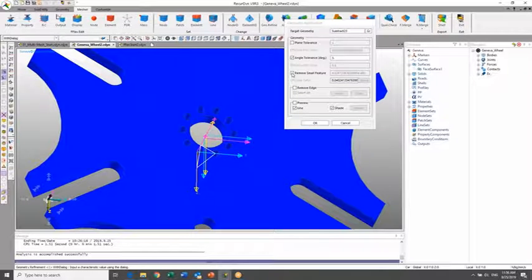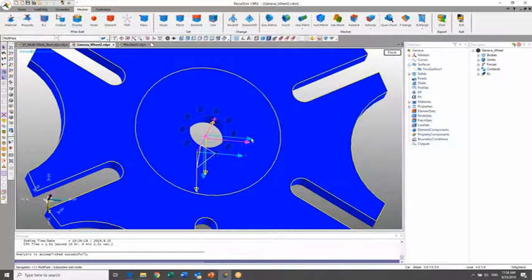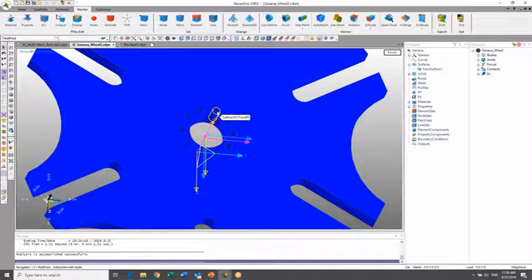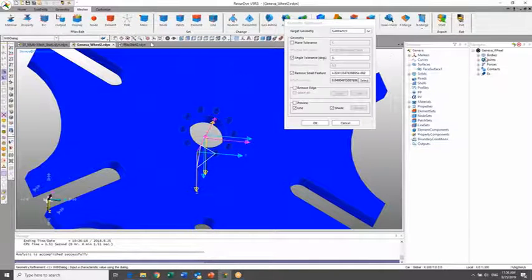And so I'm going to go ahead and check this refine small features. I'll select one of these holes, and go ahead and click finish. When I press the select button and select that hole, it actually takes a measurement of what the size of that hole is. It doesn't automatically update this field in case that measurement isn't something that you want to keep. All you're doing here is taking a measurement.